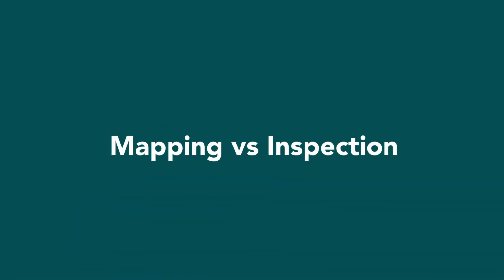Right, okay, and finally, another concept for GSD is mapping versus inspection. So GSD can have different influences depending on the end application. So if you're doing mapping, and as I mentioned before, you have things like measurements that you might want to take from the map, or you might want to do some form of modeling, and you want to understand where the model is in 3D space with respect to the real world. For all of those things, it's really important that GSD is aligned with your data accuracy.